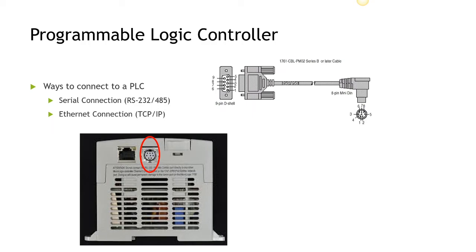The nice thing about this is if you knew the pinout, and Allen Bradley even gave you the pinout, you could make the cable yourself. The problem with USB to the 9-pin is it actually takes some electronics to be able to do that, and that's why we ordered from a third party for us to be able to connect in that fashion.